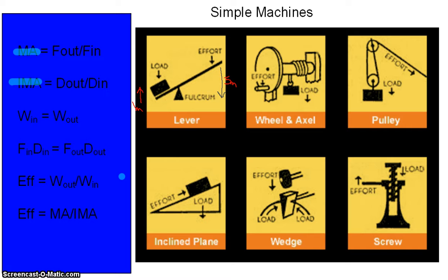So with the lever, if you're pulling down 5 meters and it's only going to lift the load up 1 meter, then you are multiplying your force ideally by 5. Now if the lever bends or stretches, that's going to reduce it some, because when you pull down 5 meters, it might not actually lift it up 1 meter as the lever bends.